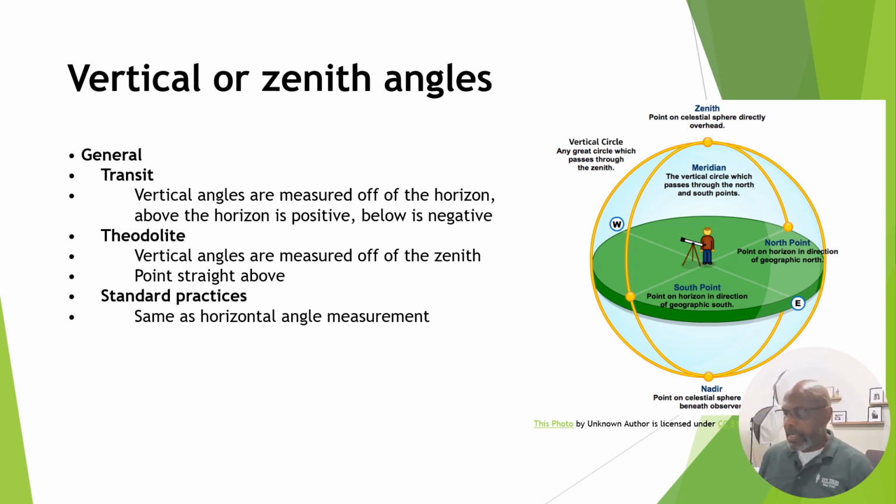So again, the standard practice is, even though the vertical angles are measured in a vertical plane, many of the standard practices of instruments used in horizontal angle measurement still apply. These include communicating, sight carefully, and read the angle correctly. Also, two other points that are necessary: make sure the instrument is level. If it's off level, your angle is going to be off. Sight the horizontal crosshairs, and sight exactly on the target, what you're looking for. Not slightly off, but exactly on it.